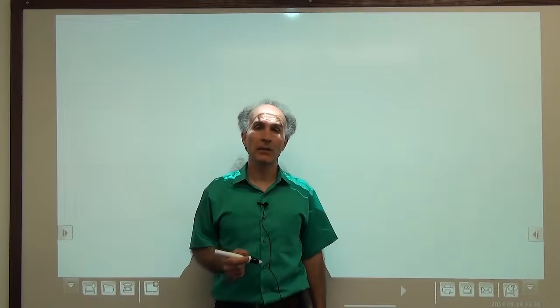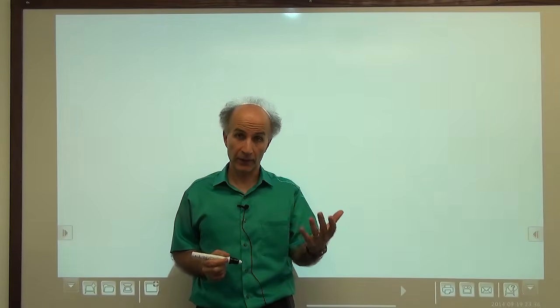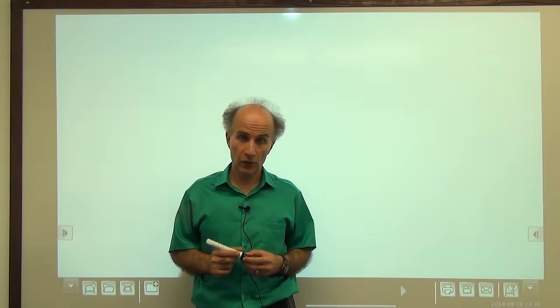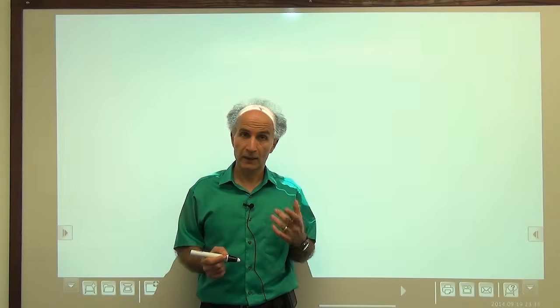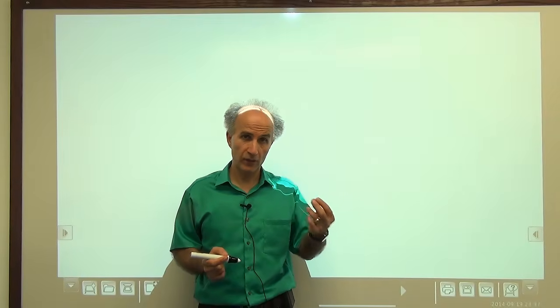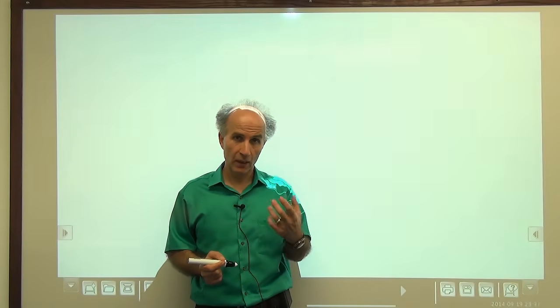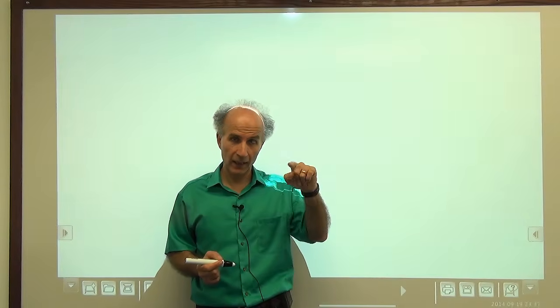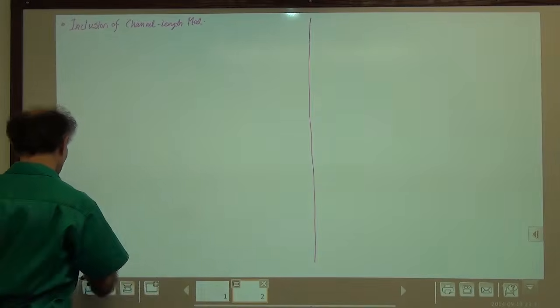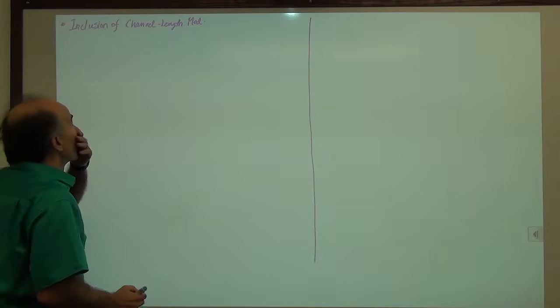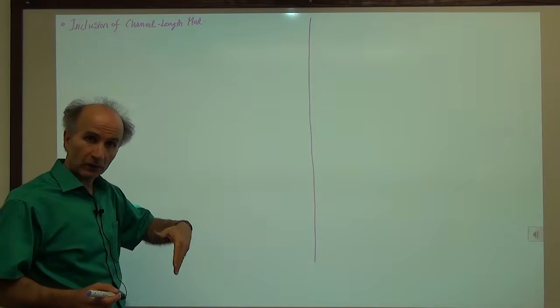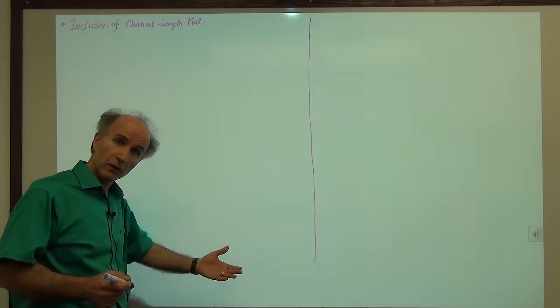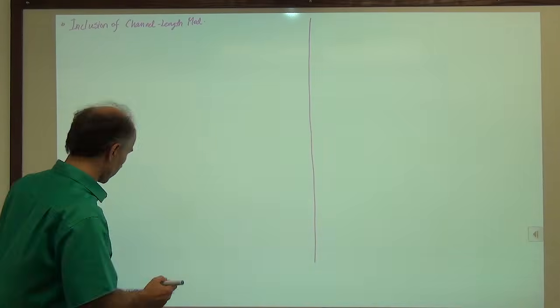All right, so now that we have analyzed a simple example of a common source stage, let's go ahead and include the channel length modulation effect in the amplifier and see if the results change. We saw that the gain of the circuit was given by minus GM times RD, RD representing the total resistance tied between the drain and AC ground. Well, how do we do that? Not that difficult. We go back to our circuit, draw the small signal model, include the RO in the transistor model, and then calculate. So that should be easy.